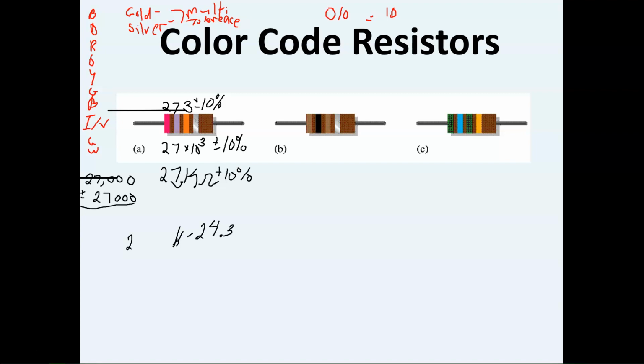All right, so it's 29.7 kilo. I forgot to move my 7 in there and was wrong. All right, so you have 29.7 kilo and 24.3 kilo. So if my range goes up to 30 kilo, that's bad. If it falls to 23 kilo or less, it's not a good resistor. It must fall in this range to be considered a good resistor.